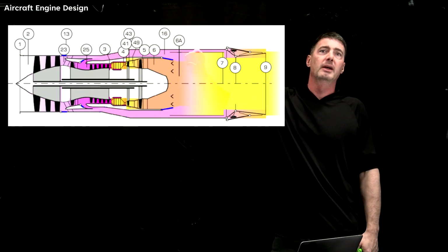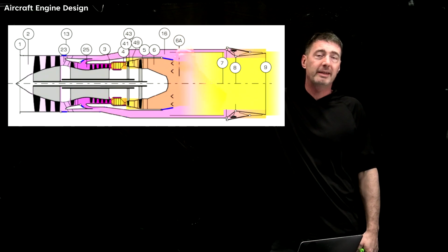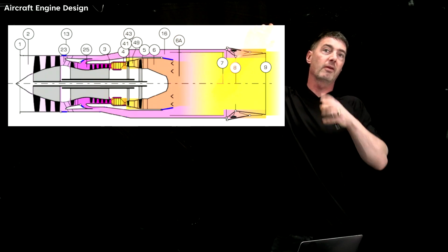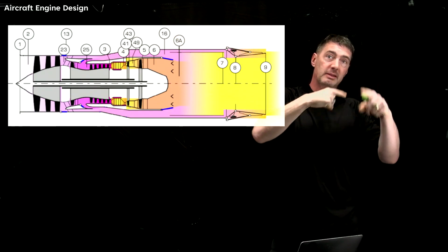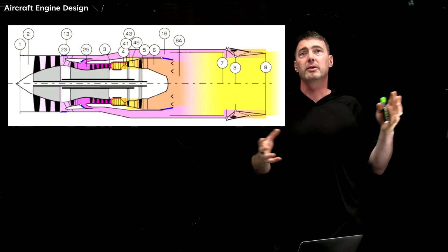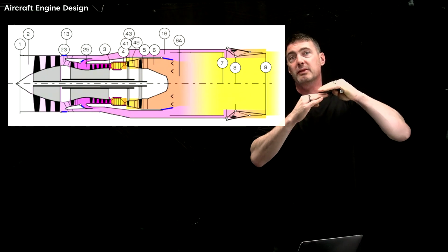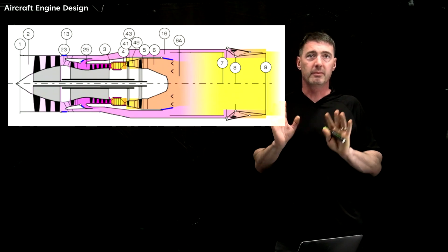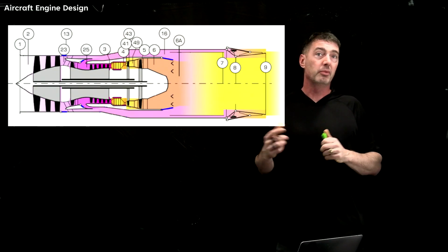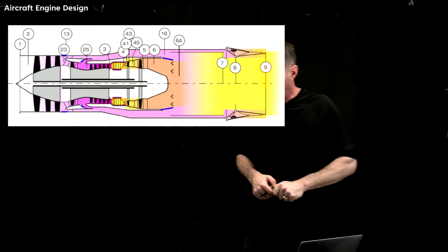When you burn things, you make them hot. In order to extract energy from the heat, you have to be at higher pressure so that you can convert that into flow and expand it over turbines. Same thing's happening in your car. Suck, squeeze, bang, blow. You're squeezing in the engine, you're adding fuel, and then you're pushing the piston. So that's where you get your work out in the car. It's all the same stuff here, just continuous in a Brayton cycle, with constant pressure heat addition.